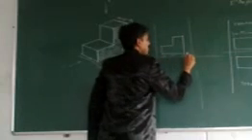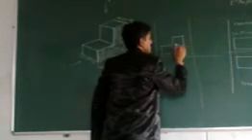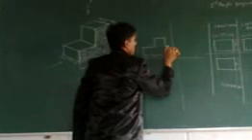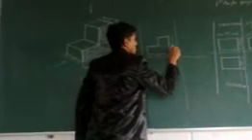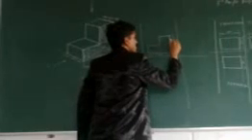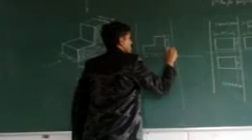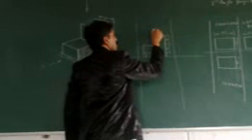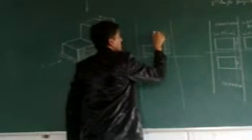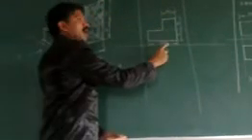So this is 100. Here there is a split. So project a line with a light line, use the eccentric, lighter pencil, and this is 30, and this is also 30. And simply show one half of the length. So the remaining is 40. That is, the remaining is 50. Why? Because we have shown the total length of it. And next, to concentrate on the top view.